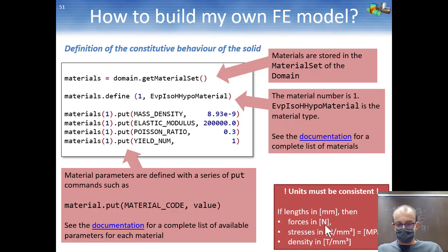and you use this kind of properties. So you see here that in order to write these numbers, you have made some assumptions about the units. So in this case, forces are in Newton, stresses are expressed in Newton per the same unit used for the length. And then you can just make a dimensional analysis of the equation.